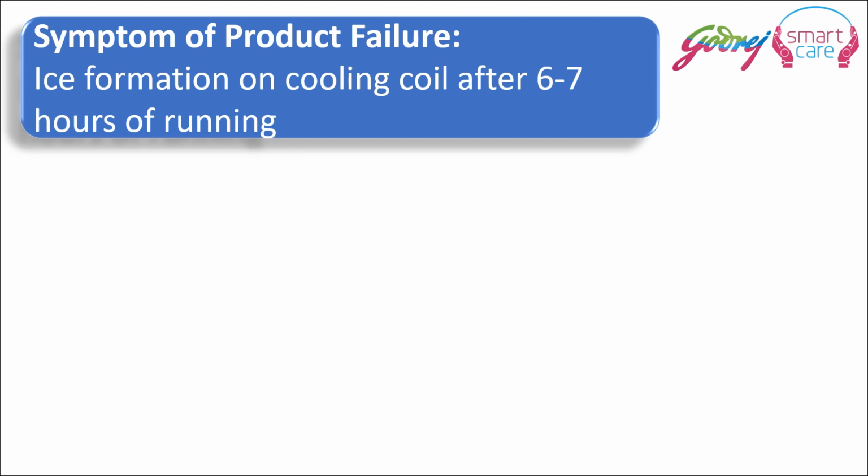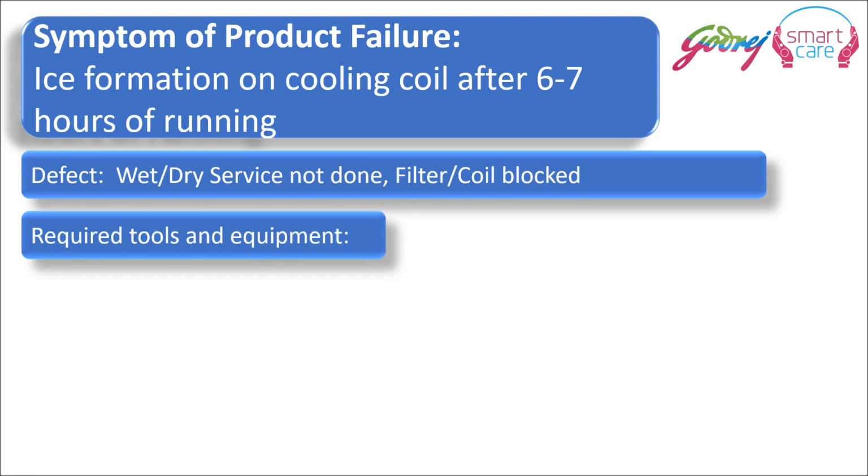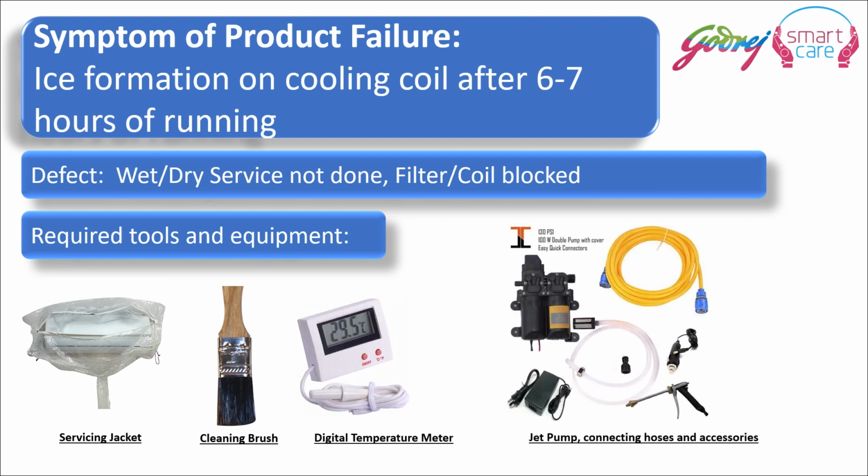Symptoms of the product failure, like ice formation on the cooling coil. The defect is wet or dry service not done, or filter or coil block. Required tools and equipment: a service jacket, a cleaning brush, a digital temperature meter, a jet pump, connecting hose and accessories.